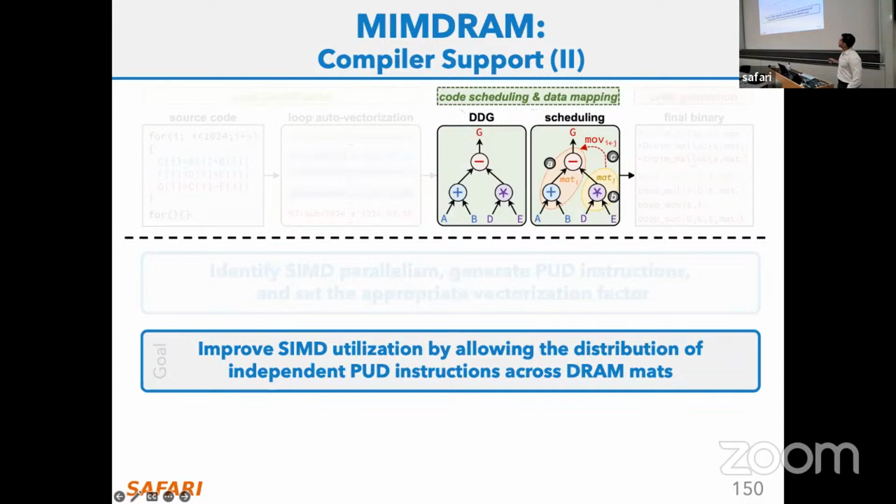And so basically what we do in this scheduling routine is to identify those patterns and then use some metadata to tell the control unit later on that, when you fetch this instruction and you fetch this instruction, execute them in parallel, but when you fetch the third instruction, wait and execute it in serial, also in serial to the previous 2 ones.